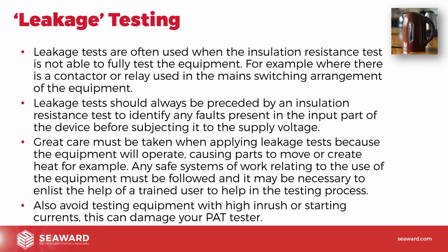Now, if you were to just do an insulation resistance test on that piece of equipment without turning it on, all you're really doing is checking up to the input side of the power supply. If there was excessive leakage or a fault within the power supply, chances are we might not detect that, because effectively the power supply is not connected until mains is applied to it. So actually the button on the front of the computer is not a mains button. There isn't 230 volts run to that button like a switch on a kettle, say. It's a soft button. It's a button that electronically drives the power supply.